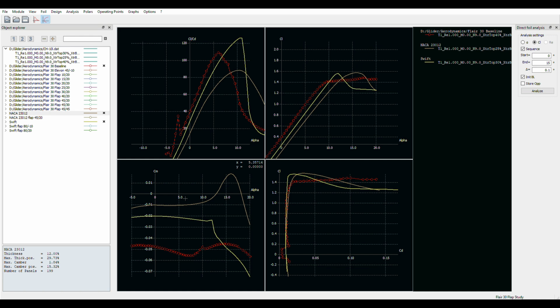That's because at normal cruise speed on these aircraft, that's about what the mean aerodynamic chord operates at, somewhere between 900,000 and a million on the Reynolds number. So I just made them all a million, and we're staying away from problematic areas like 750,000 and 500,000. That's for another discussion later.